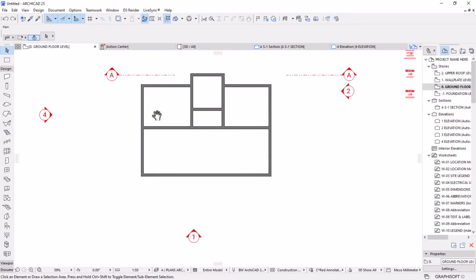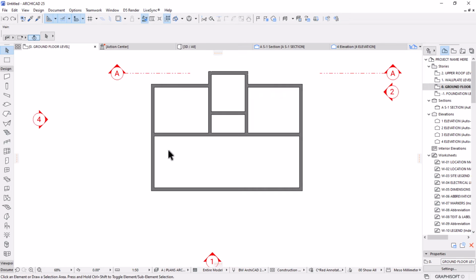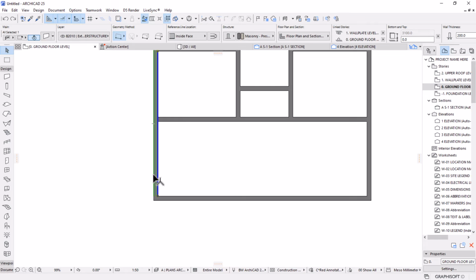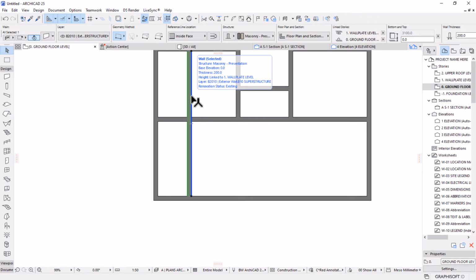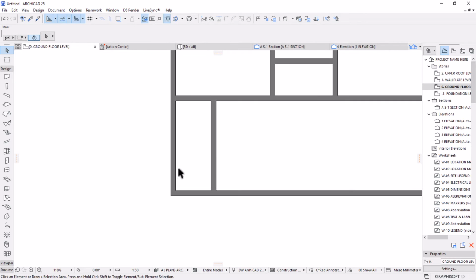Okay, another thing is we have the guest toilet on this side, in this area here. I'm going to select this wall, Control Shift D, and put it aside to the other wall, then Control D again and move it by the width of the toilet. This toilet is going to be, let me see, I can just use 1.4, right? Then I can get rid of this material by holding Control, then clicking on that.